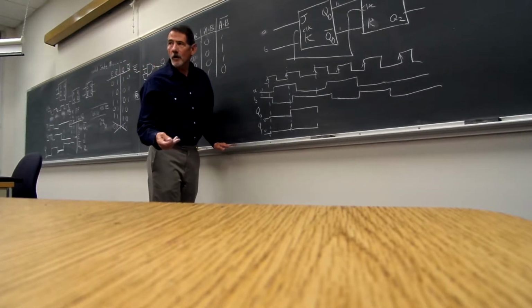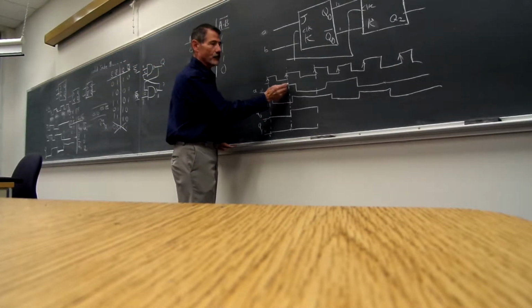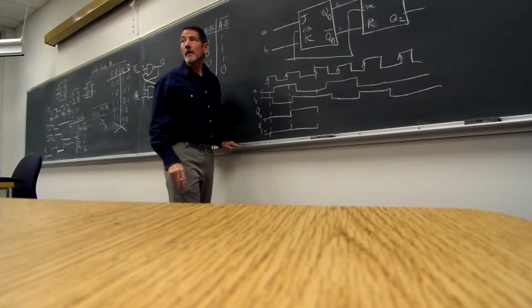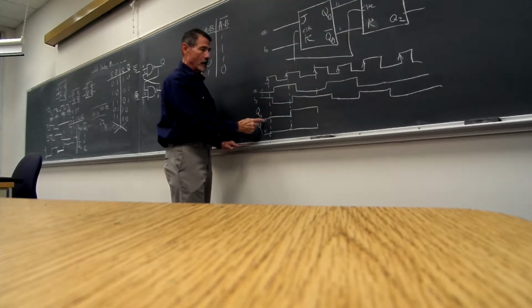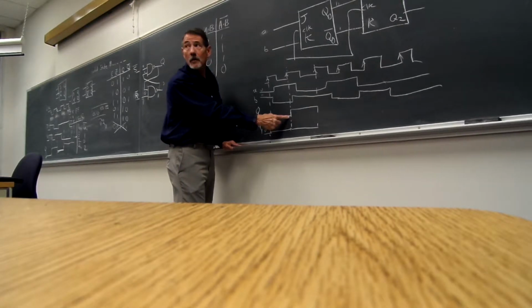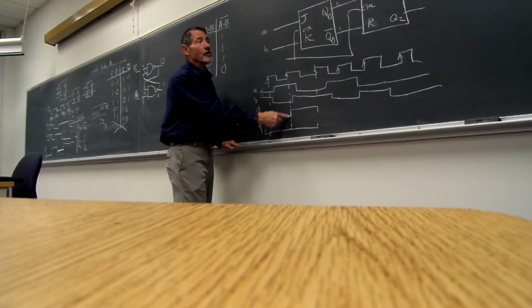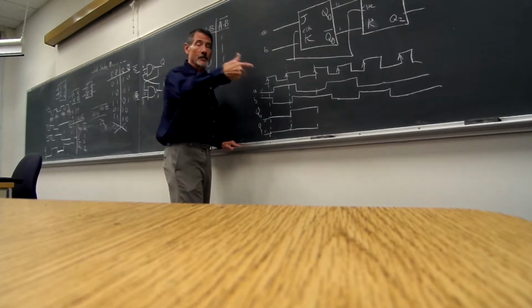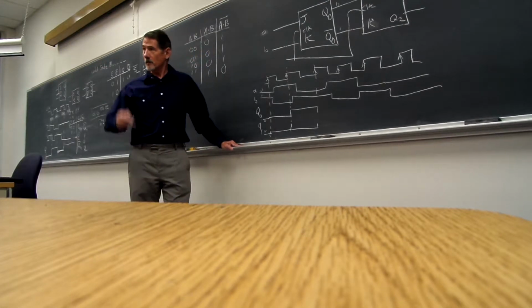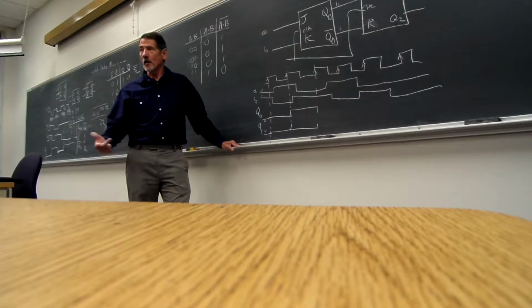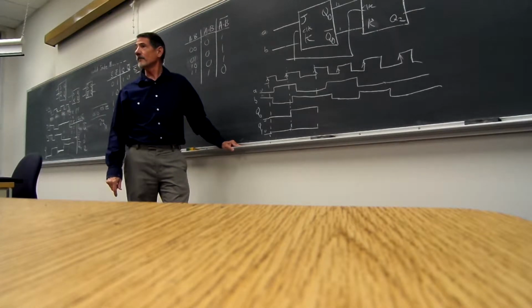You have to look at this edge. What are the J and the K inputs? The J is what Q naught is doing, and that's a 0. And this guy is a 1. So it's got a 0, 1 going into it. You clock it. It says reset. It already was a 0. It just stays a 0.